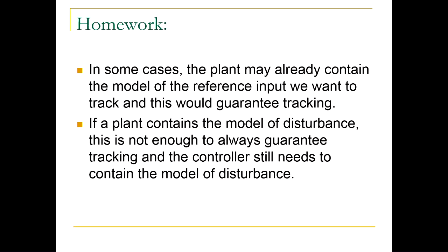By the way, in some cases, the plant may contain the model of the reference or disturbance. This is left for homework. I would like you to assume that the plant has an integrator, but the controller doesn't. Look then at the steady state errors that you get from reference step inputs and disturbance control inputs.